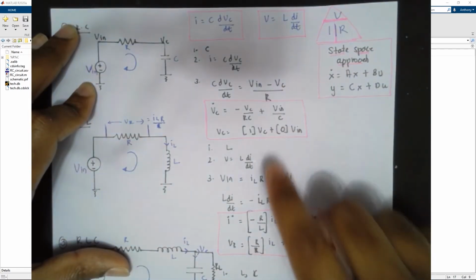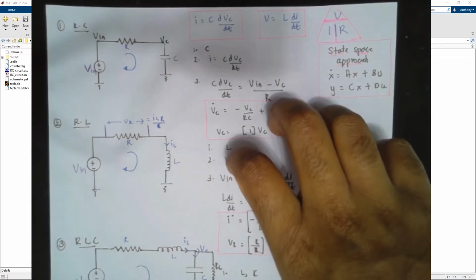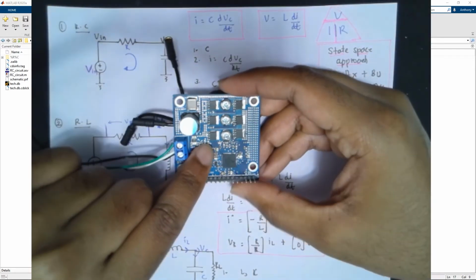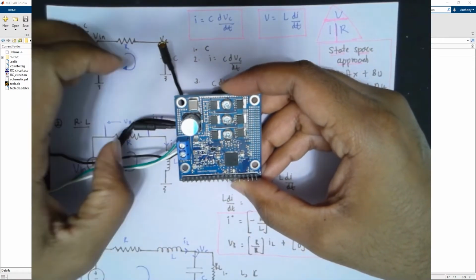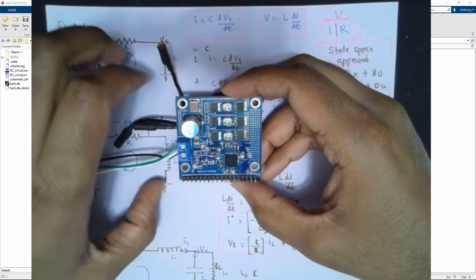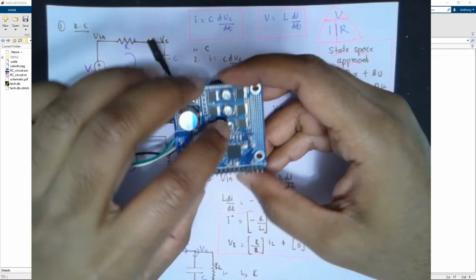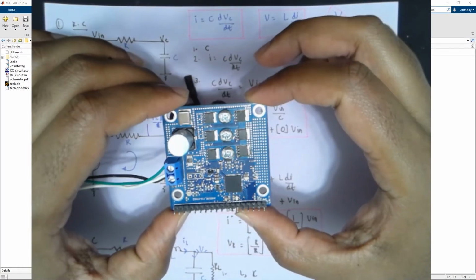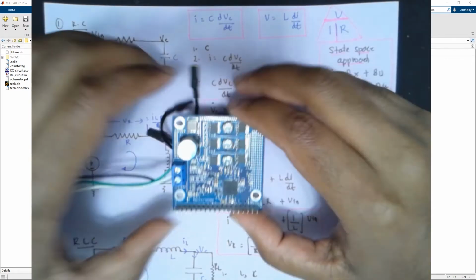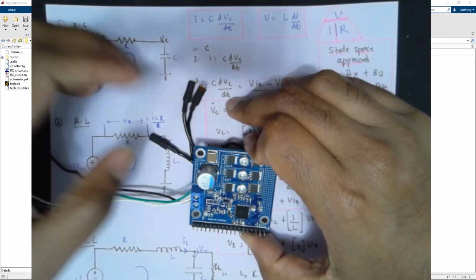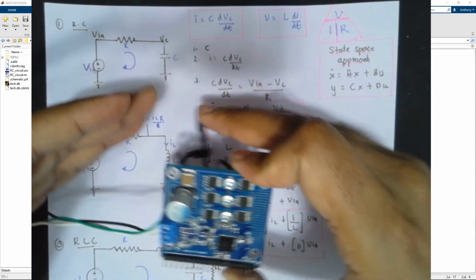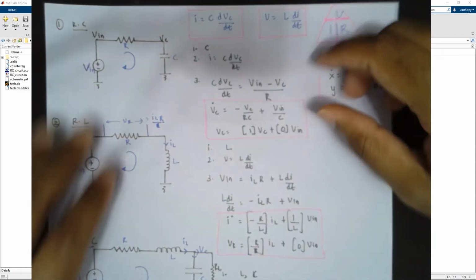This is important because as we make more of these boards, eventually you'll be simulating all of this through a SPICE model, and the more we're able to capture the parameters of the board into simple lumped circuit models, the better. So there's an advantage to just understanding this.